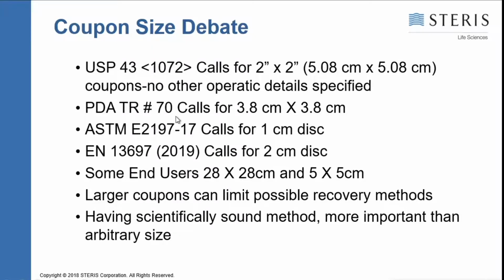PDA's Technical Report 70, which I was a co-author on, says to use 3.8 by 3.8 centimeters. That's a possibility. But we do recommend the ASTM method. E2197-17 uses the 1 centimeter coupon, and the European method uses a little 2 centimeter coupon.